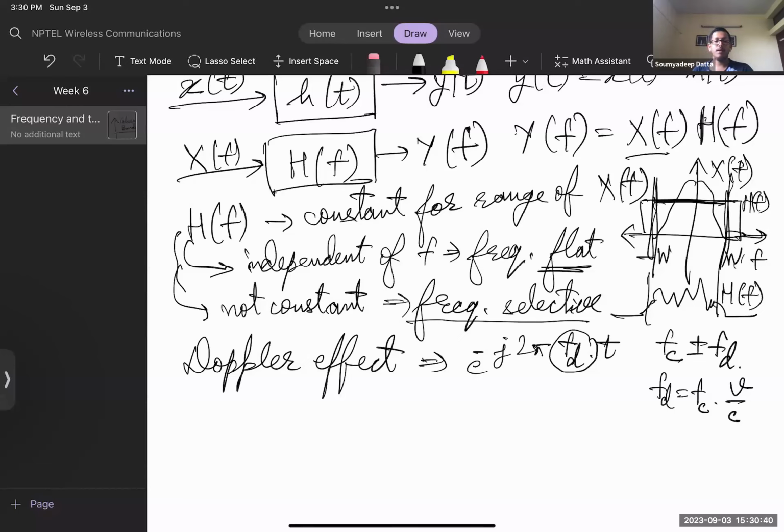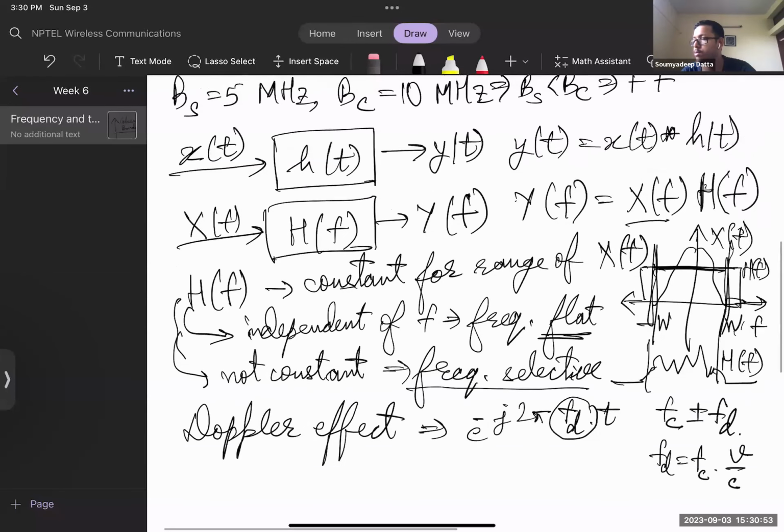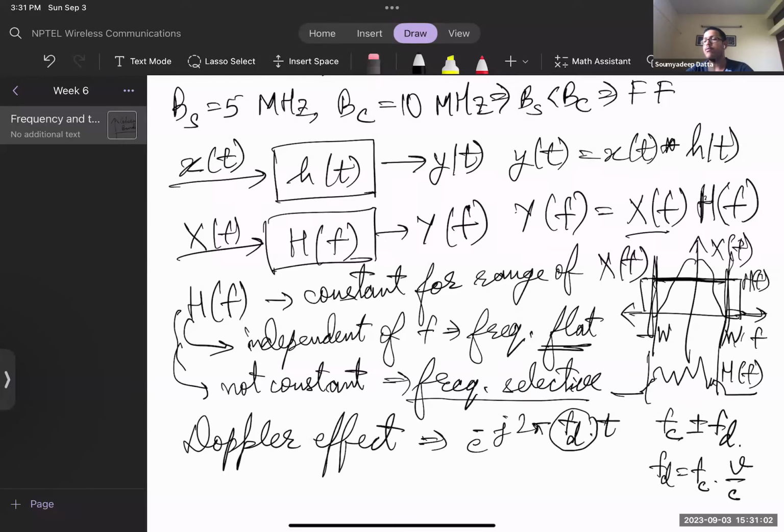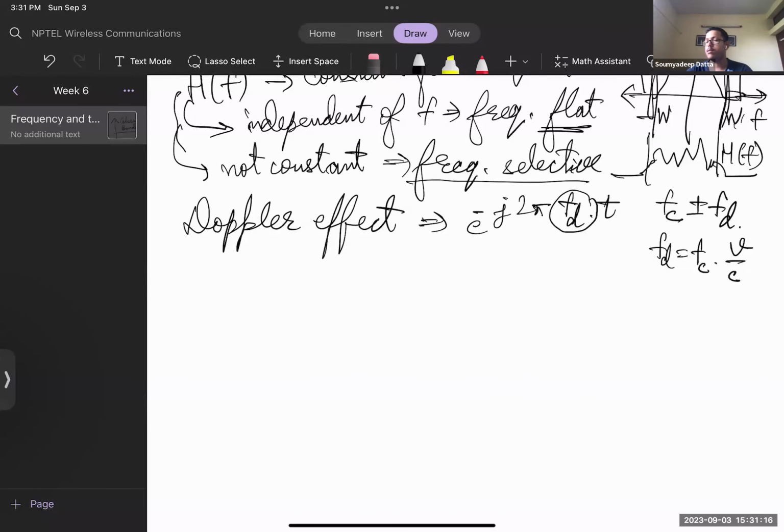You're not a physicist, so you won't always know. But what we can do is measure channels. We will have an idea of the coherence bandwidth, which is the variation in frequency for which my channel roughly remains constant or doesn't fluctuate that much. Here, as you can see, you can only construct a very small box. Maybe a little less, like this. This kind of small box is your coherence bandwidth, where your channel response is not fluctuating too much. That is basically what you compare.